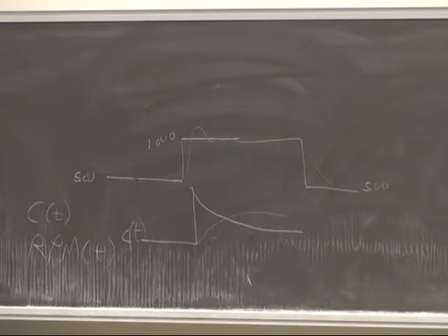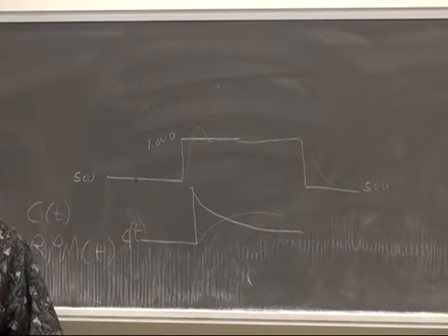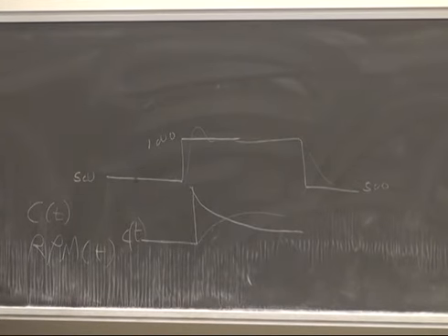So you need to output the control voltage and the RPM not only for grading, not only to satisfy the TA, but because it will help you debug. Do that first. Don't do it last. It's not an added feature. It is part of debugging the lab.